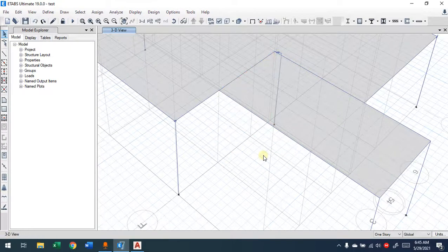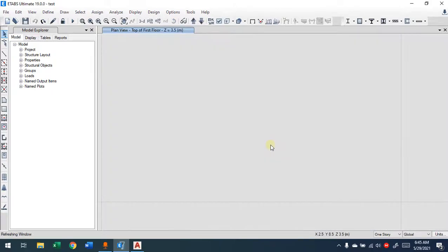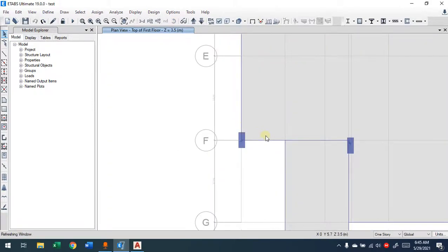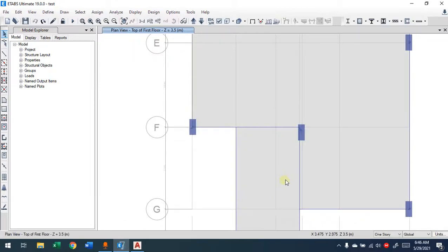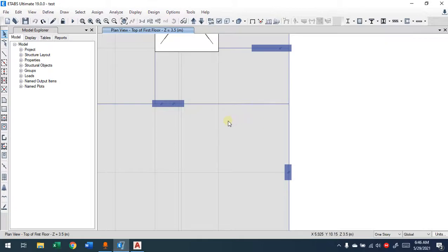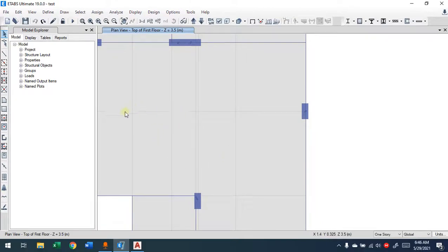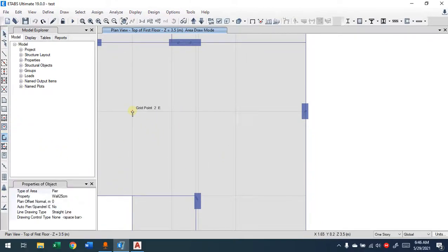This is if you're going to draw. But remember, when you're using draw tools, you need the reference point. The way I did it here was just for explanation. You cannot just click without knowing the exact location. Normally you have the beams around it, or you have the grid line at least. You have the grid lines, you go over the grid lines and you place it there. Normally at the location of a shear wall, you don't have beam. Let's say it will be between these grid lines here. So in that case, you follow the grid line. Let's say I'm following the grid lines here.